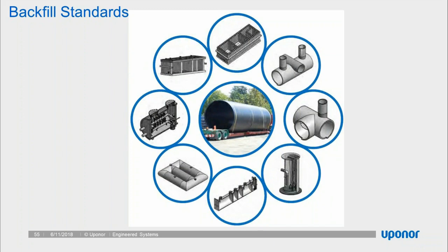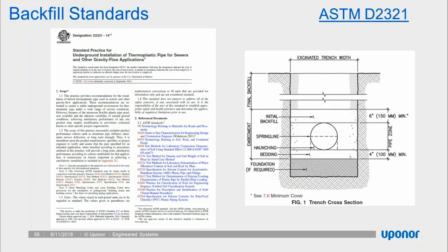And the last thing I have before I hand it off to Tripp is backfill standards. Backfill is an important thing. Poorly backfilled structures can have differential deflection. They can have undue loadings applied, and they can pop and leak. So we want to make sure that any structure that's buried in the ground is backfilled correctly with high quality material compacted to the proper level of compaction specified.